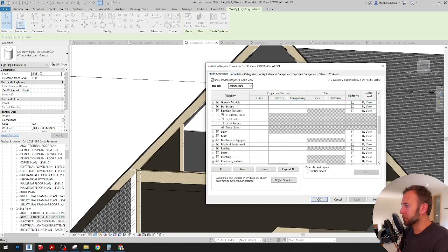So I wanted to mention while we're looking at the lighting, in vaulted ceiling systems, you should always use gimbal style, which gives you a little more flexibility in terms of aiming that light or pointing it downward. In many cases, fixed lamps are used as well, but I like to have a little bit of directionality. So I've got a gimbal. It's just a typical recessed light, but you're able to change the angle of the light projection.